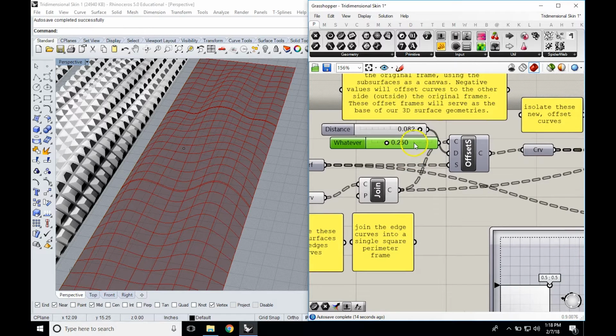And then one last thing about number sliders before we move on is if you want a number slider set up exactly, like you want it set within your range on the exact number that you want, there's a little shortcut command. You can double click, and then let's say I want a number slider that's between 0 and 20, and I want it set to 4.3.